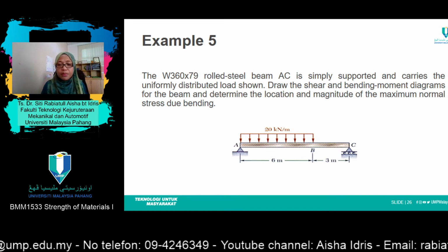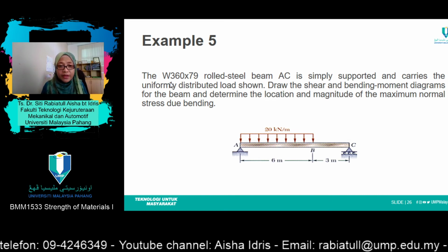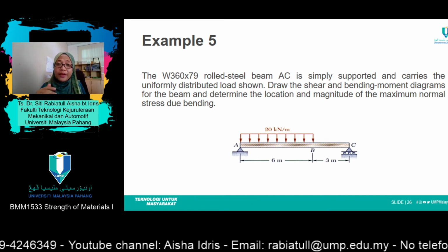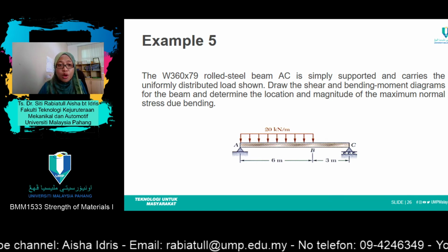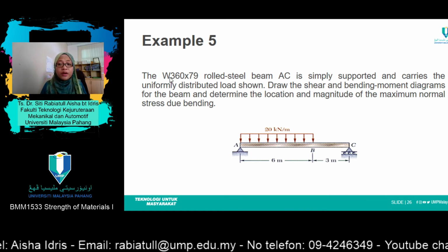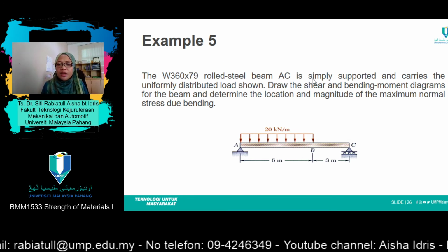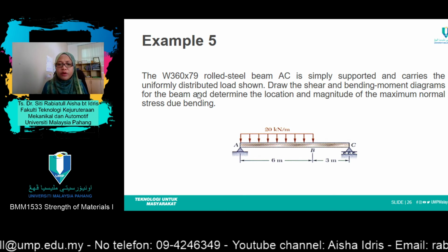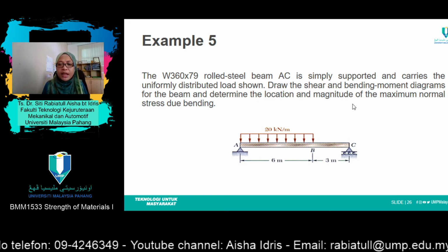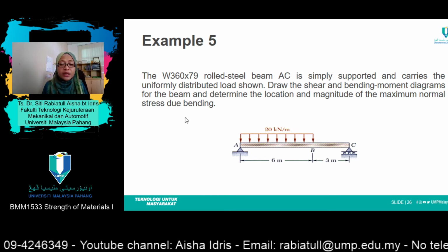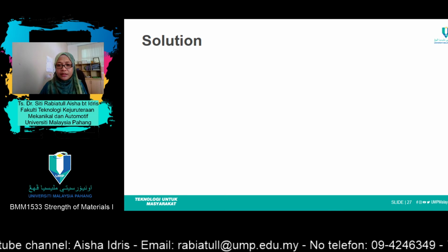Okay, move on to example 5. For this case, the type of beam is given to you, so you just need to find the value of S in the list of tables that is going to be given to you, or you may find these types of beam at the end of your textbook. The beam is simply supported and carries the uniformly distributed load as shown. Draw the shear force and bending moment diagram for the beam and determine the location and magnitude of the maximum normal stress due to bending. So let's solve this problem together by using the integration method.